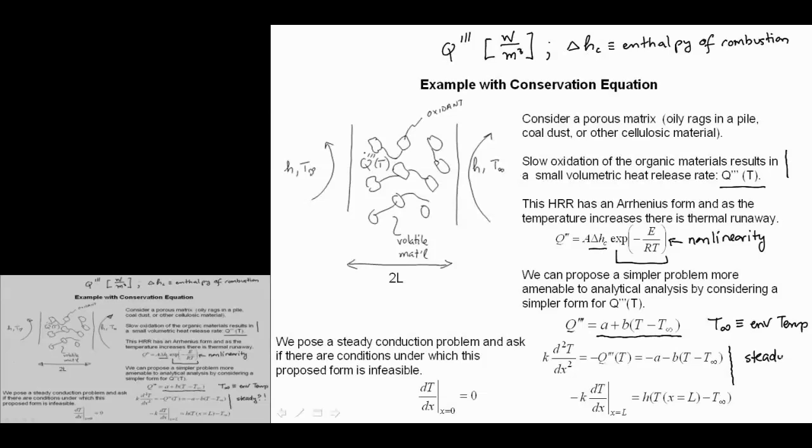And I understand that as I make this system larger, I expect the temperatures inside to increase. Let's make sure we understand that. So let's think about a simpler problem. If you had a constant heat generation, Q dot triple prime 0, between a fluid with heat transfer coefficient H and temperature T infinity, and somebody asks you what the temperature distribution looks like in this,